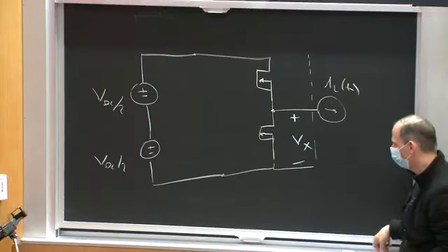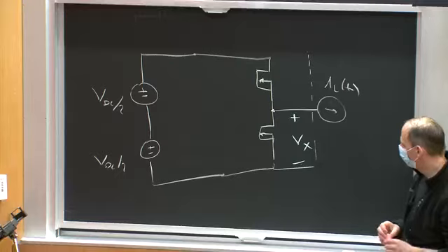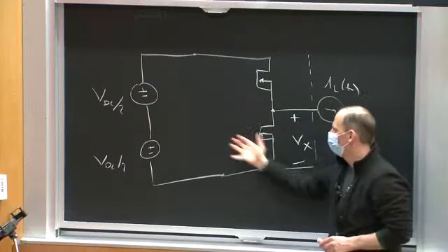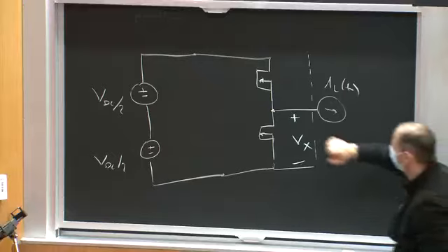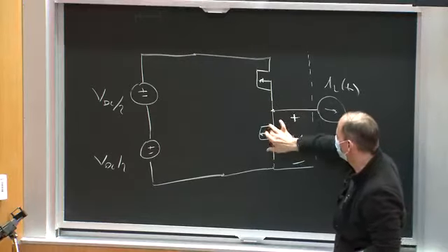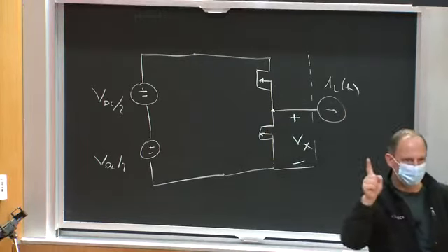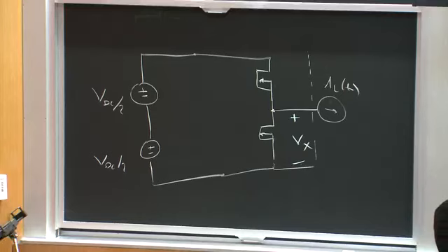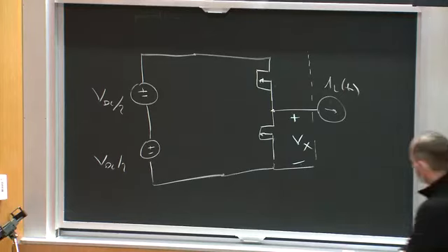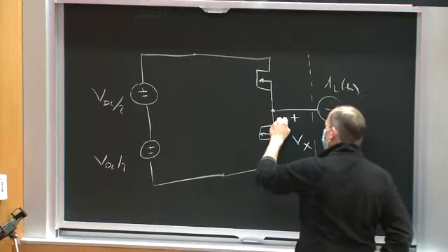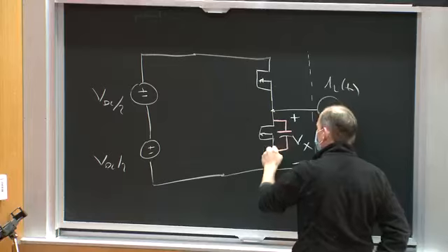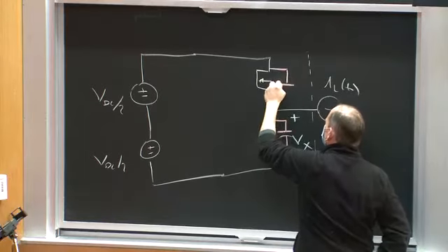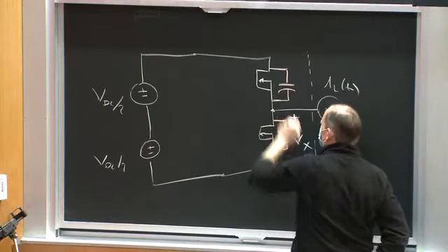And here's one thing you could do. Maybe we can look at this thing and add some auxiliary circuitry that lets me switch between these two devices anytime I want, but will give me a soft switch transition. All right? Here's how we could do it. Maybe the first thing I'll do is I'll add some capacitance across each device, and that would include the intrinsic capacitor in the device.